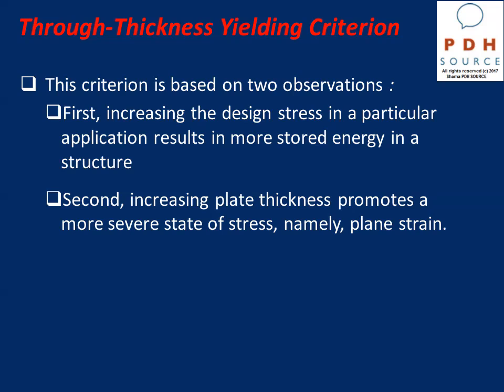So basically, as we increase the applied stress, we get more stored energy. The second observation is that increasing the plate thickness promotes plane strain behavior. And according to this second observation, one can expect that a higher level of fracture toughness is required to obtain the same level of performance in thick plates as would be obtained in thin plates.